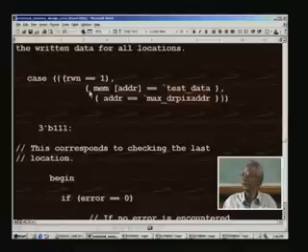In this case what it says is: read the memory whose address is given in ADDR, that is from the external RAM which is in the test bench, and compare that with the test data that we have already written, I mean it is initialized in the test bench, that is all 5s here. If it is equal to 5, the read content, then only this whole thing will return 1, that corresponds to the second bit here.